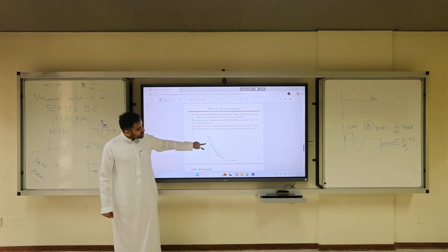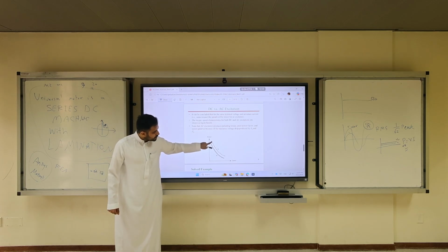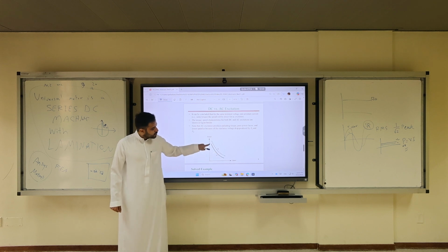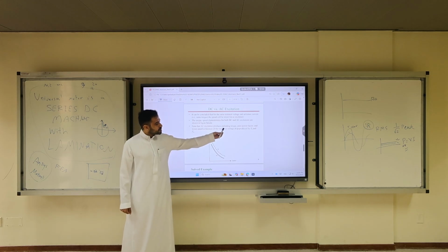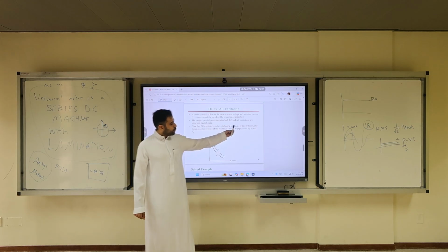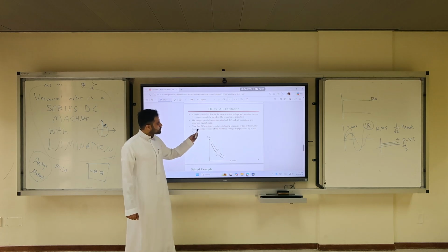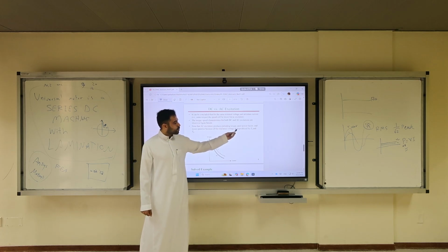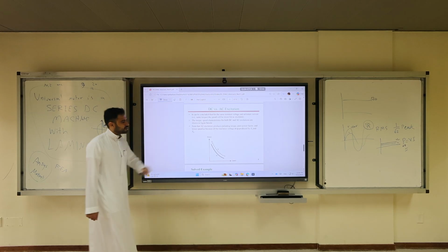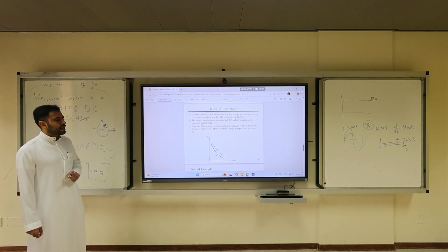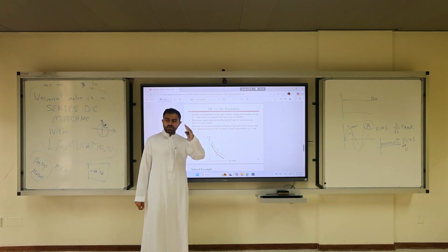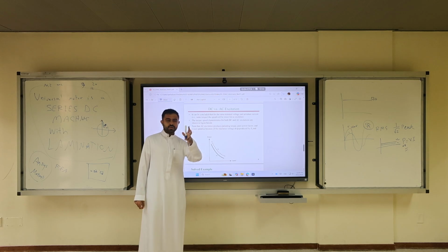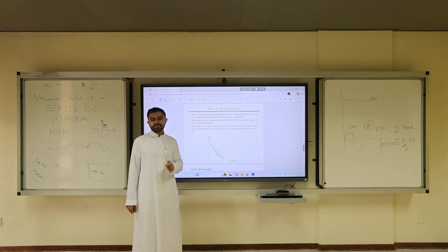The torque speed characteristics: remember this curve, at DC the torque speed curve is this one. For an AC, it's this one. Note that the AC excitation produces pulsating torque, poor power factor, and lower speed because of the reactance voltage drop produced by XF and XA. This is not relevant to our class directly. But I remember I told you about the pulsating torque. Torque is not smooth. How do you get the smooth torque? Power electronics. Yeah, but there's a simpler solution.